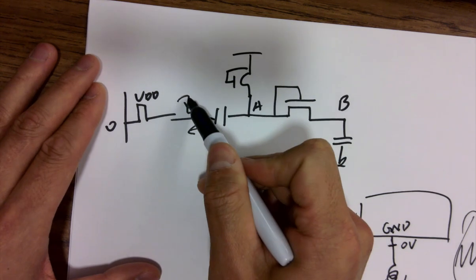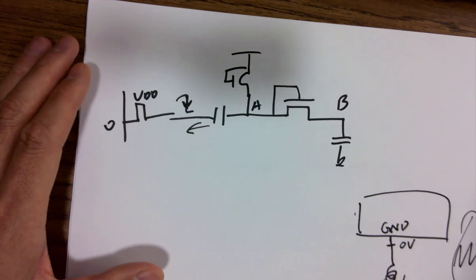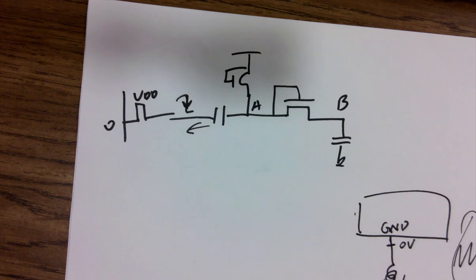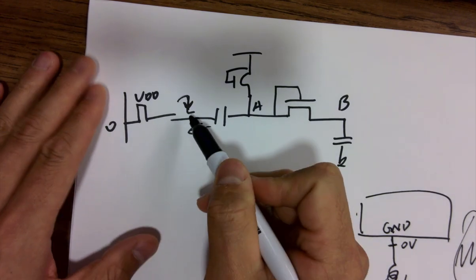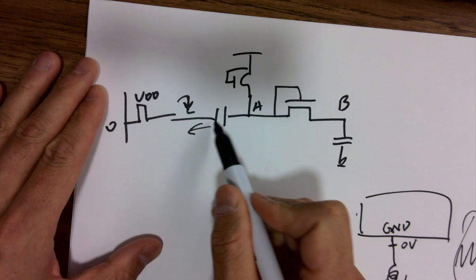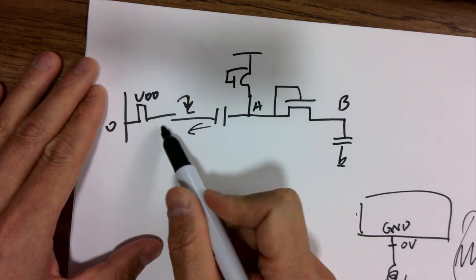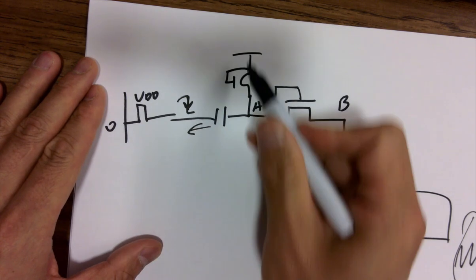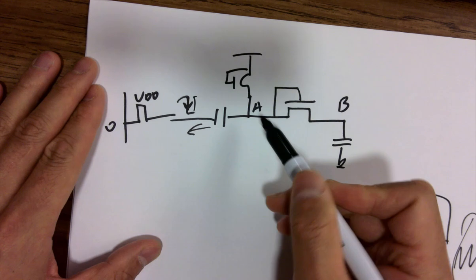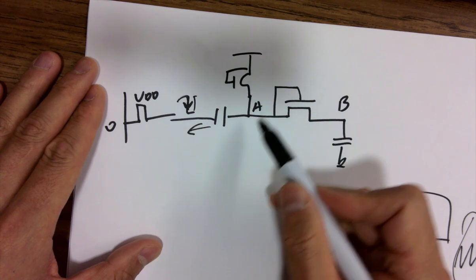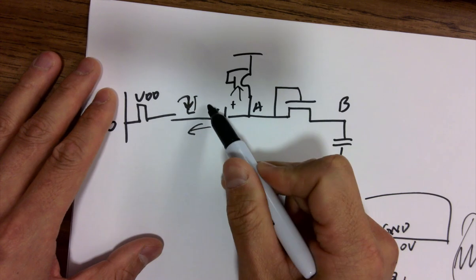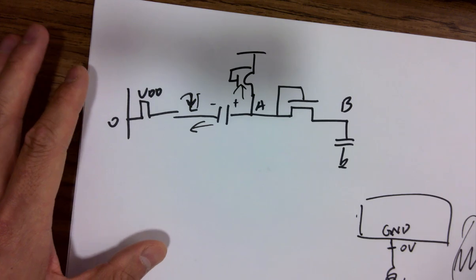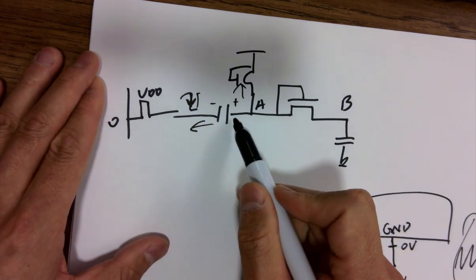So a falling edge is considered as an AC signal. It's changing. It's not a steady signal. It's not DC. So it's an instantaneous AC. It's changing, so the AC will pass this guy, right? That's why it's able to pull charges through it. It's passing the capacitors, it's pulling charges, and then whenever it goes up, it's trying to push it back, and there's no way it can go back. It's blocking it. So eventually it stores the charge across the capacitor.